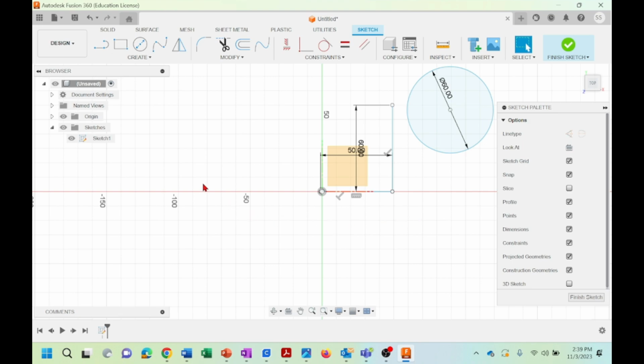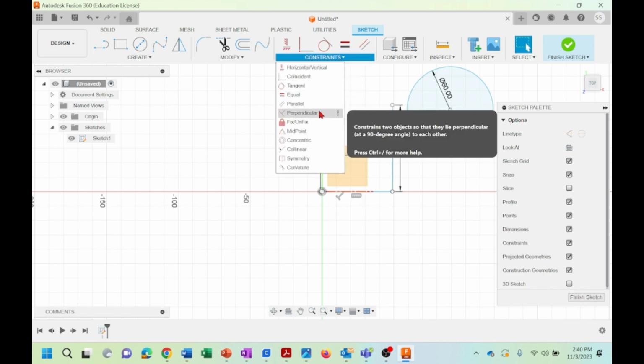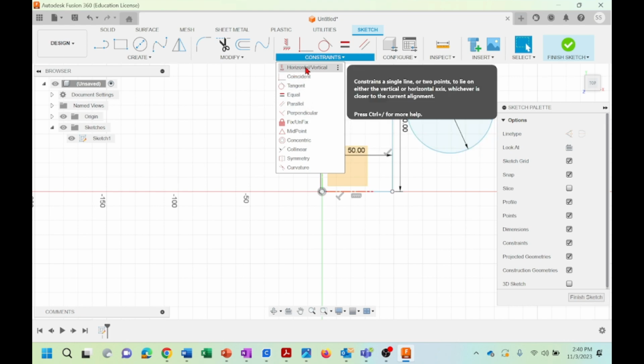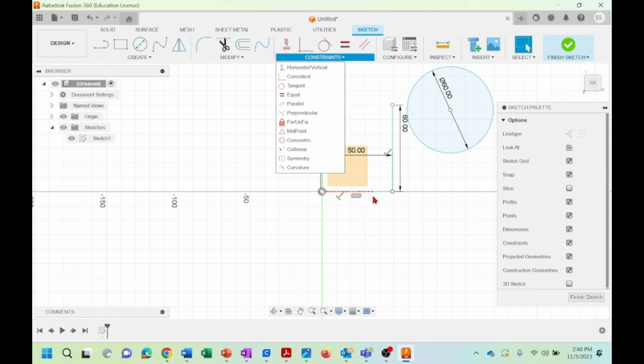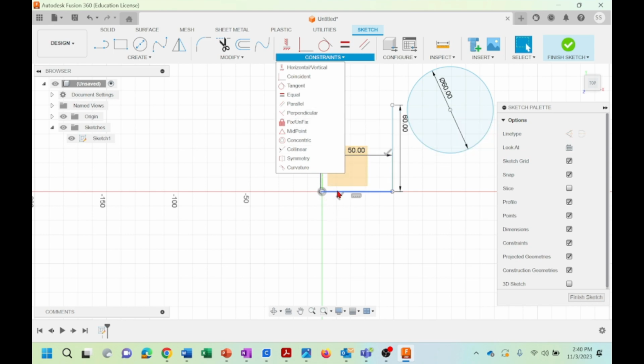As you can see, whenever you add a few more drawings, you see the constraints, and they have different shapes, right? See this one back here, what does it say? It says you have a constraint. Find that symbol, which is the horizontal or vertical one. It says this is horizontal to the axis. What does this say? This is the symbol that says it is perpendicular to the y-axis that you have. Here is the same thing, you see these constraints again.